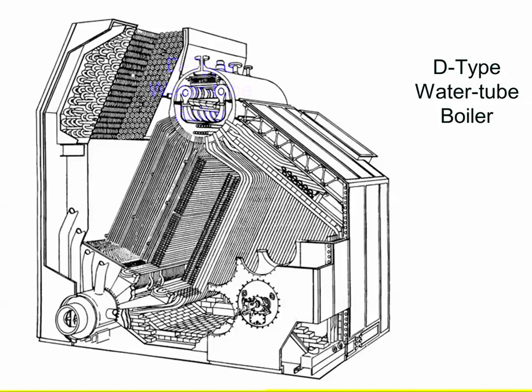I can remove that oxygen. I can take that flue gas, and these are big ships with very, very large tanks, so I need a high volume of gas. The boiler will produce that gas, and I can recover that waste heat to run the steam turbine.